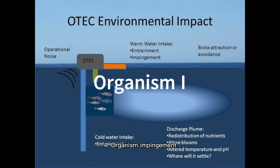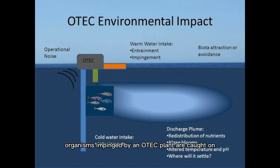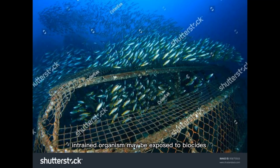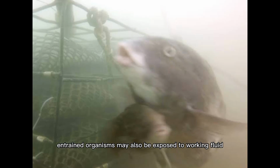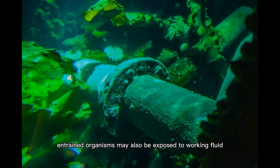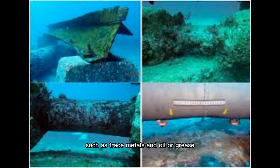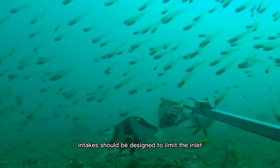4. Organism impingement. Organisms impinged by an OTEC plant are caught on the screens protecting the intakes. Impingement is fatal to the organism. An entrained organism is drawn into and passes through the plant. Entrained organisms may be exposed to biocides and temperature and pressure shock. Entrained organisms may also be exposed to working fluid and trace constituents, such as trace metals and oil or grease. Intakes should be designed to limit the inlet flow velocity to minimize entrainment and impingement.